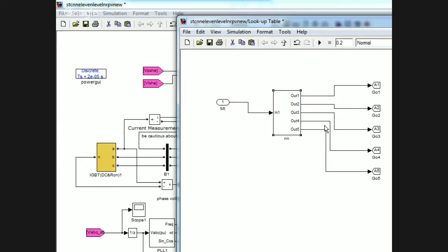When you do optocoupling, automatically this digital circuit, which we call the control circuit, and your power circuit will be isolated, so there will be no damage to your system. So these things, when you do it in hardware, you have to keep in mind.